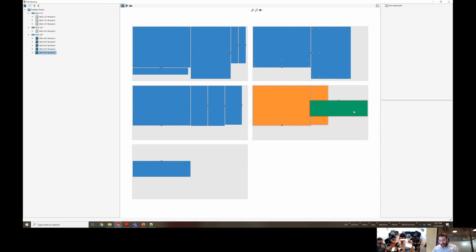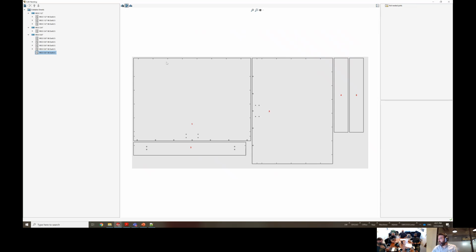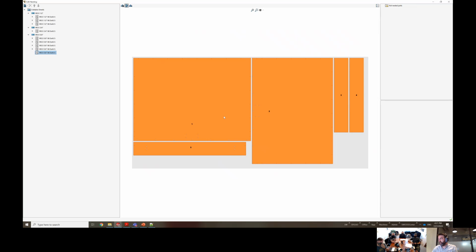So I can try, for example, here to enter one part to another. There you go. Yeah, okay. I thought you had to go with assembly. So that's nice. I can also change the order of cutting here. So it's 1, 2, 3, 4, 5, but I can do 1, 2, 3, 4, 5. And here I can also add my bridge between parts. And that will be something we see at the end, of course, on the toolpath.